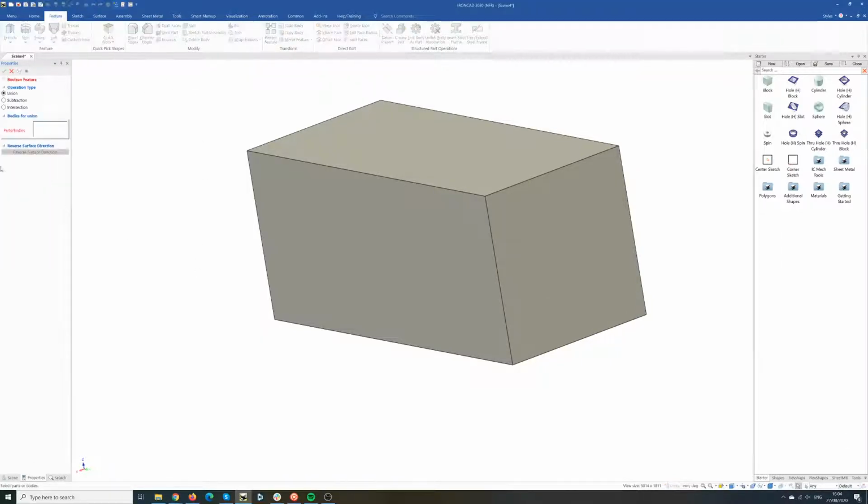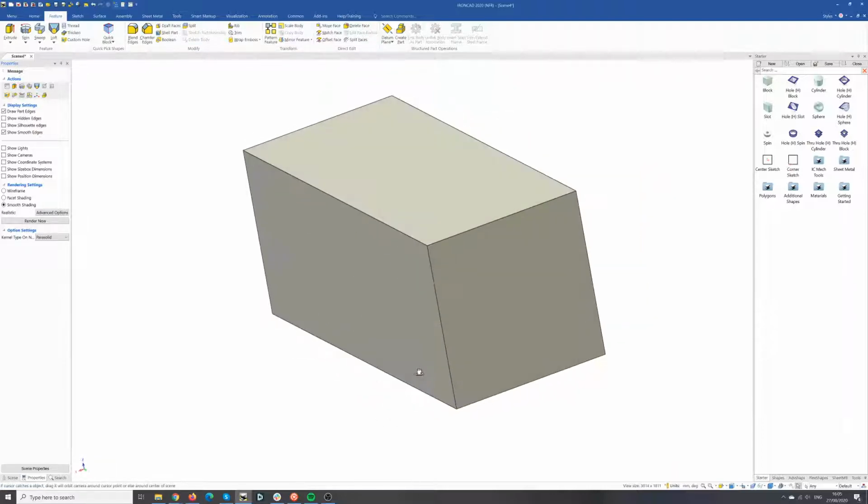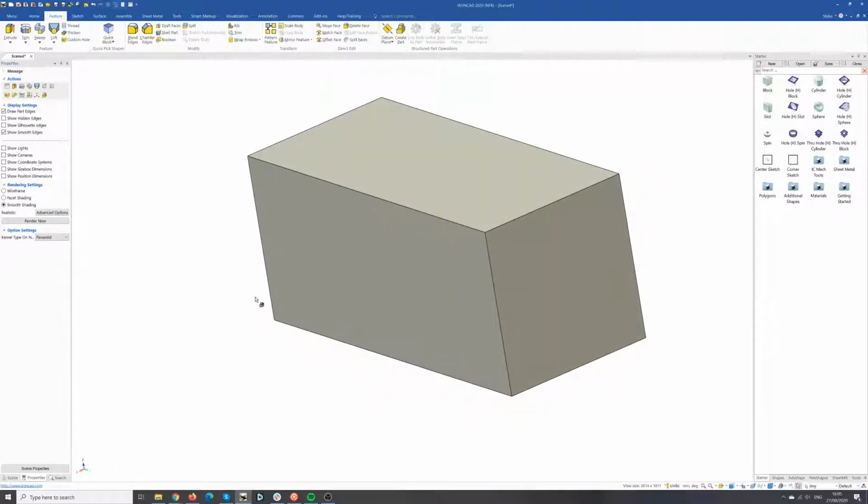ask you a question. You want to do not a union, you want to subtract. What is the main body you want to subtract? So this is the one I want to keep, and this, and now it's saying what are the parts of the body for this subtraction. You can't select it. Well, there is another way you could do it. If you actually click on that part there by going in the properties, you can then actually select the two, say done, and therefore you've got that part subtracted from that block.